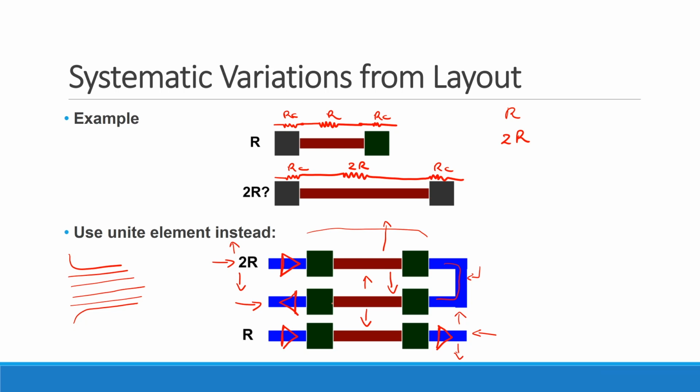You're absolutely right. Now, by the way, this is again a processing thing. The reason why the direction may actually matter is because when they do the doping, that's generally at an angle. And it's at one unique angle for the entire chip. So things that go one way are not exactly the same as things that go the other way.